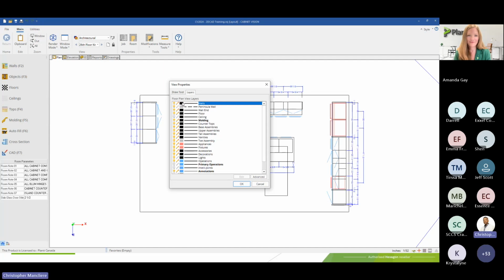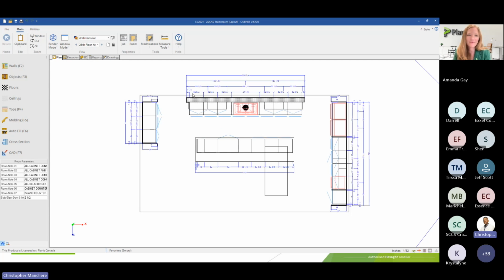The third option is the color of the object. You simply click on the color selector, and then you can set a color for the specific layers. In my particular setup, most of the objects are black, except the peninsula wall being gray, and the appliances and fixtures being pink, as we can see on the screen right now on the right side. If I want now to change, for example, the color of my annotation, I can change it independently than the rest of my cabinet. That's why they are blue in my example. So if I click OK now, I have my walls back on my screen.